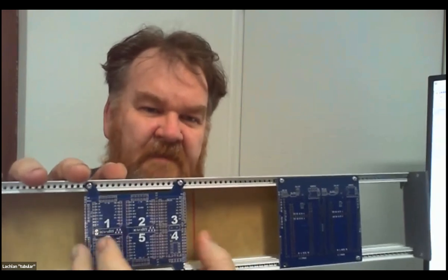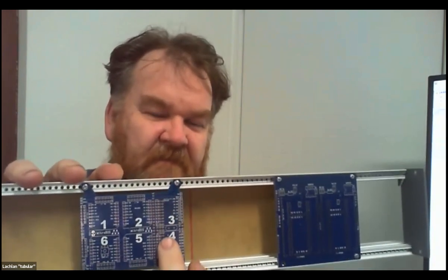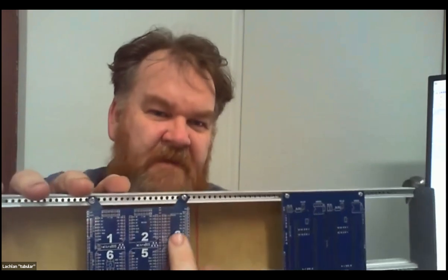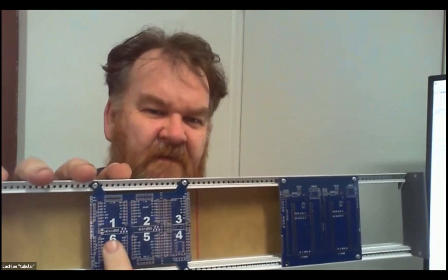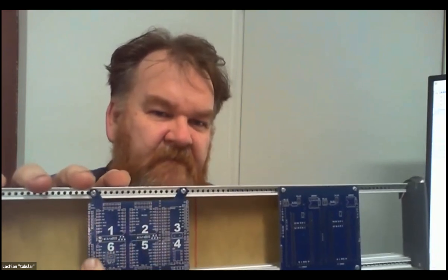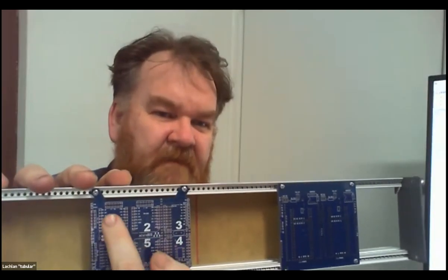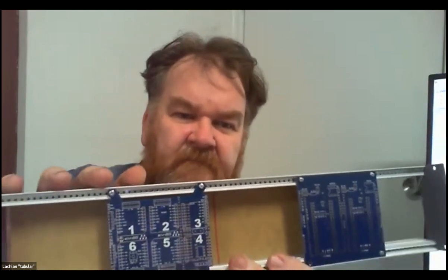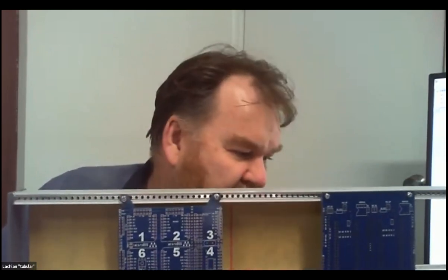So this is like self-contained, and the CPU, which is on here with its 32 or 64 pins, is sort of moving across to these sockets, the Clic sockets, and also we've got accessory headers, like P2 accessory headers around the outside. So for every I/O pin that originates here, we're going to 2 locations, one where the Clic module is, and one where the accessory module is. And they're in a slightly different order.